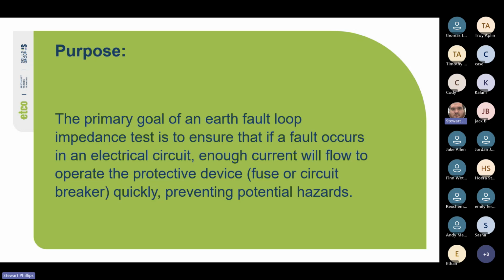If your impedance is too high, it can be one of two things: your cable isn't big enough and there's too high resistance in the cable, or there was an issue recently in Wellington, I think one of my coworkers found it, where the transformer wasn't earthed properly; there'd been an issue with the earth, it had broken or something. So sometimes they need to fix the earthing at the transformer.